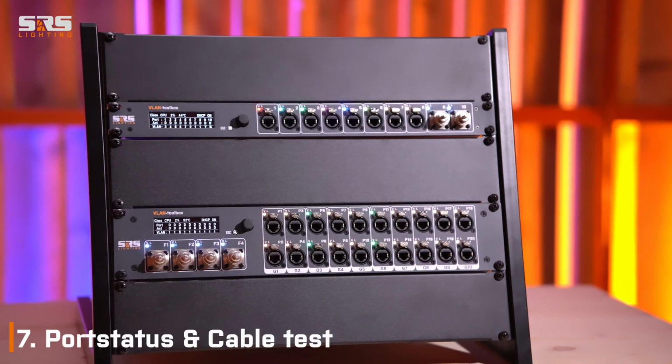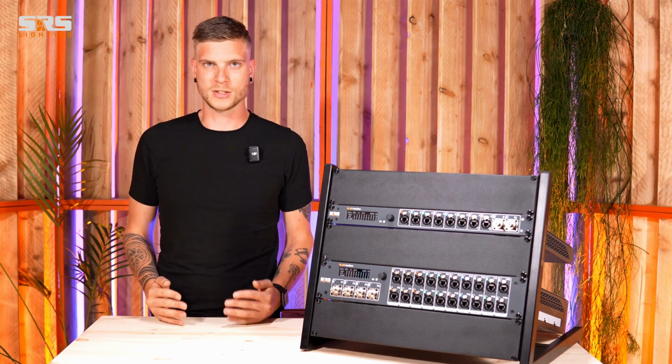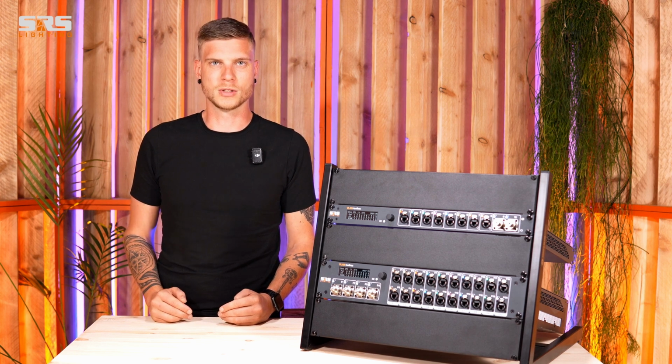In this chapter, we demonstrate several other useful features of the VLAN toolbox. You can easily check the status of each port, including the power consumption for power over Ethernet, network load, and the assigned VLAN. Turn the data knob to go to the line port. Now select the desired port number and use the data knob to switch between VLAN settings.